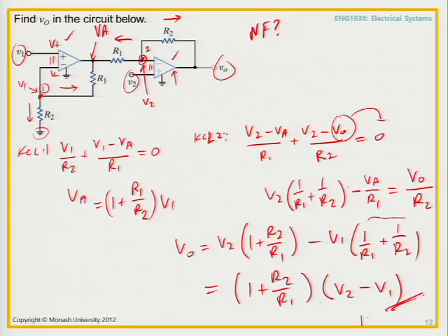Okay, so what is this circuit doing? It's doing stuff, yes. It's not doing nothing unless I've put nothing into it. Sorry? It's changing V out with respect to the resistors. Yes, but I wouldn't give you many marks for that. What is it doing to the inputs? Looking at the difference between 2 inputs and then multiplying it by a gain factor, 1 plus R2 over R1. Yeah?